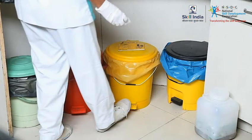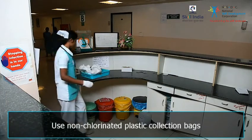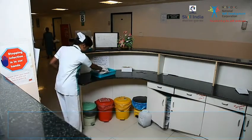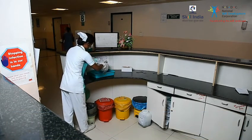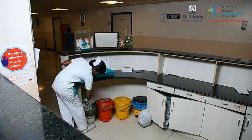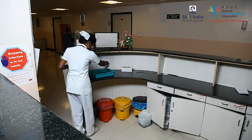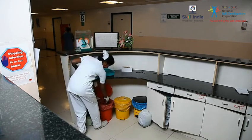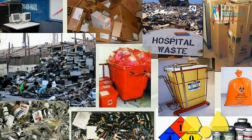Sterilize or disinfect waste materials associated with viral, bacterial, or other agents infectious to humans. Only non-chlorinated plastic collection bags are used. This ensures that the items are not being recycled or reused by rag pickers. Bags are removed after they are two-thirds filled with biomedical waste. Waste collected daily is transported to the designated storage site or deep burial pits.